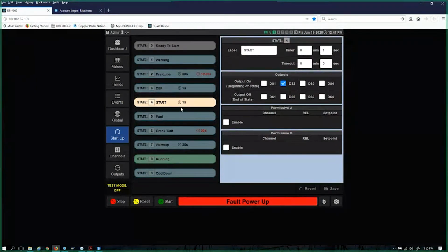Now, I don't know how long that engine's going to pre-lube for, or how long it's programmed to crank or anything, but because we have the timers for the Class B and the Class C startup, I don't need to know because I'll trigger on when I see RPM. But I can do some safeguards if I wanted to on this section.